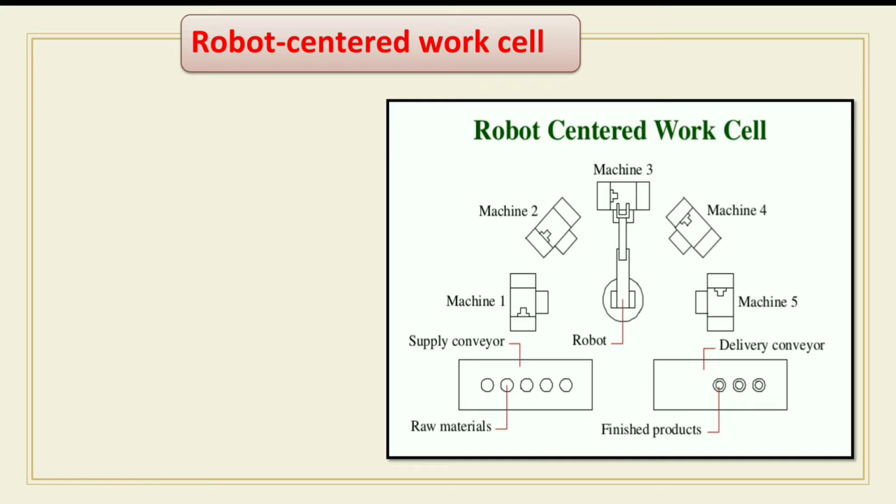One of the very first applications required the robot to unload the part from the die after each casting cycle and dip it into a quenching bath. Other production machine applications require the robot to both load and unload the work part.